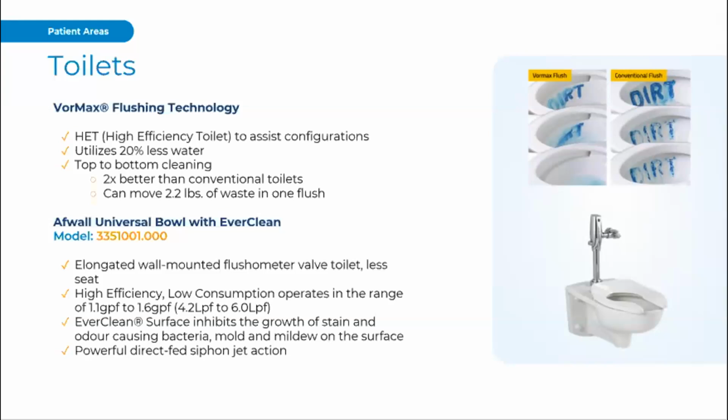It's the most effective scour of a bowl in a tank type at an ultra low flush volume. These can get, I believe, down to 3.8 liters per flush, although 4.8 liters per flush is more of a standard. However, if we're trying to be both water conservative as well as effective in our scour and waste removal, then there are some options out there.